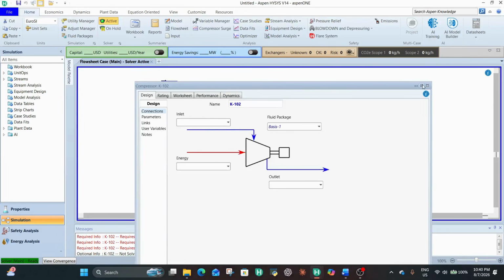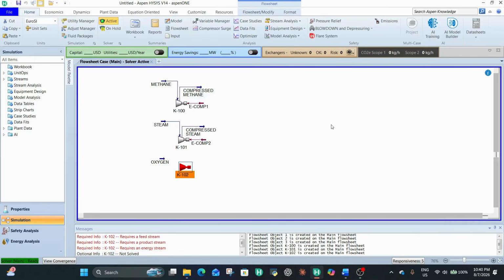Do take note: oxygen is supplied, in an engineering scenario, by an ASU, air separation unit, where it collects air and separates nitrogen from oxygen and some negligible other components present like argon. An ASU, so basically take the oxygen. In case you're wondering why you wouldn't just take air and use it for the partial oxidation.